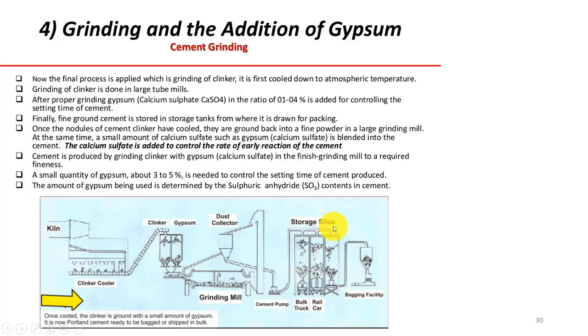Originally, cement is stored in cement silos to prevent moisture. If the cement catches the moisture, it can abruptly cause hydration, and it can set, and it can become a useless material, which cannot be used for construction if it catches a sufficient amount of moisture content.